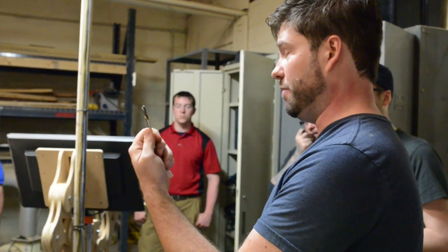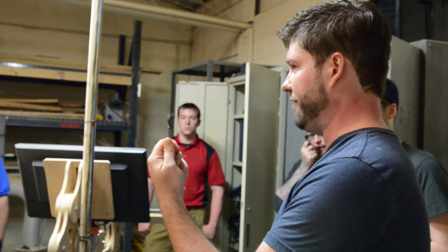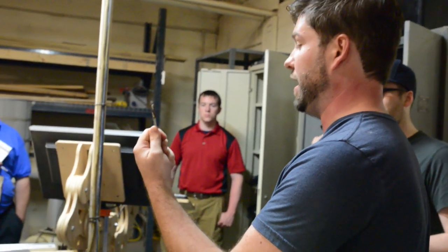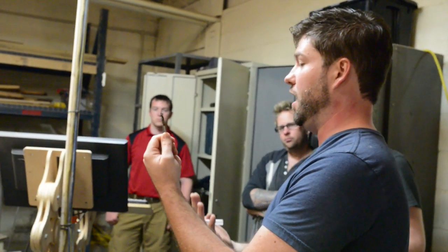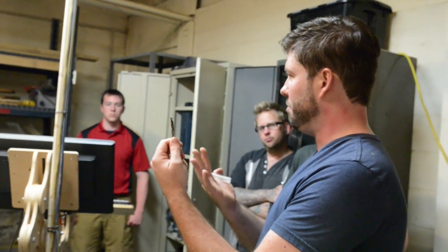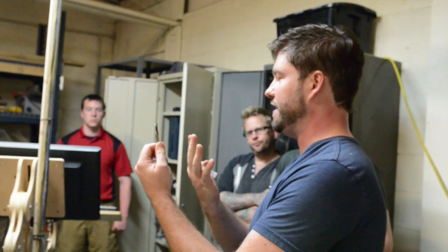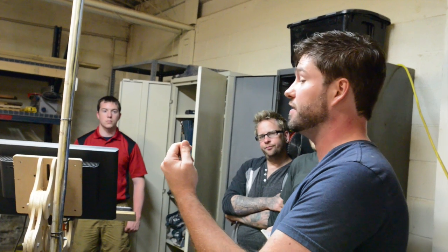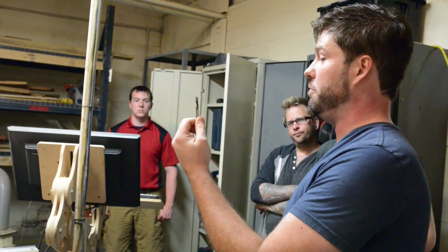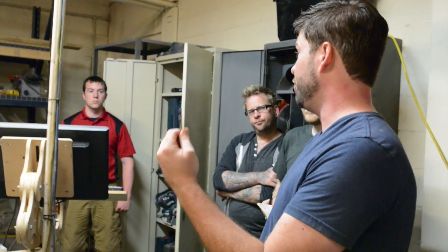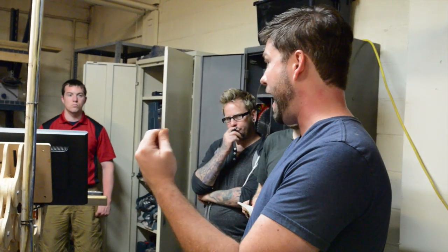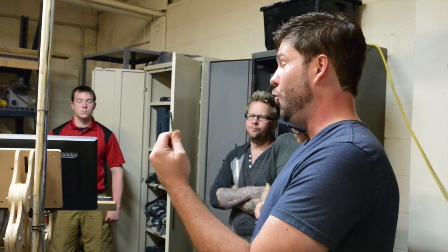We're not going to be using this today, but I always tell people about these because they'll save you a lot of time. This is actually a spiral bit, but as you look at it, you see that it changes directions on the bottom quarter-inch of the bit. You can cut through 3/4 inch plywood in one pass at 3 inches per second without any tabs.